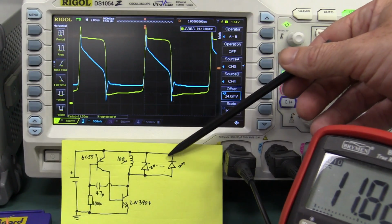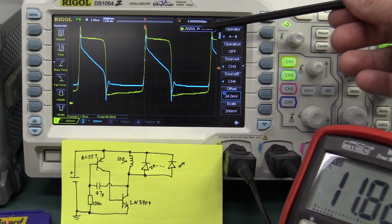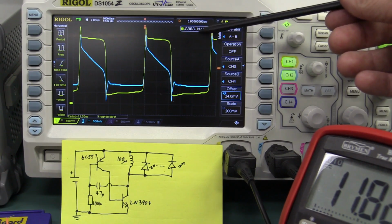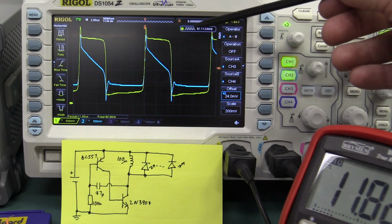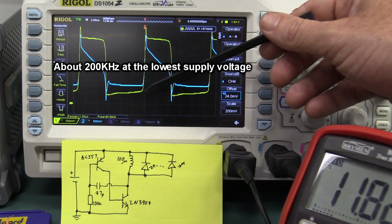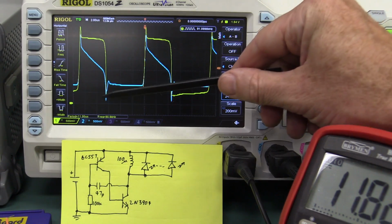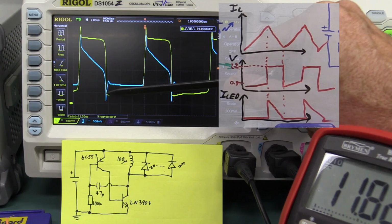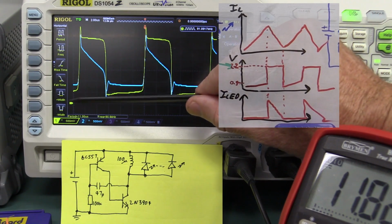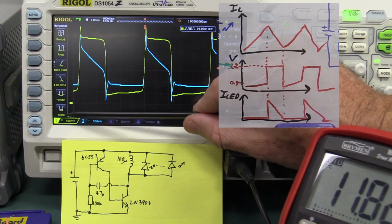And we're just probing a couple of waveforms here. Look, the oscillation frequency is around about 91 kilohertz. So I was kind of in the ballpark of a couple of hundred kilohertz. We'd expect that to change with frequency as well. We might test that in a second. Anyway, the yellow waveform here is the one I drew on the board. And here it is side by side. And I said it had started at about half a volt and then worked its way up. And does it? Well, here's the baseline down here, and we're at 500 millivolts per division.